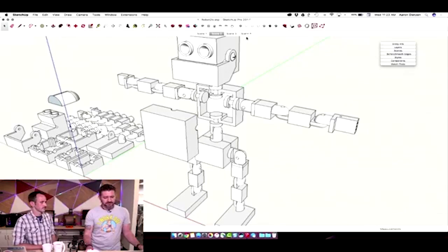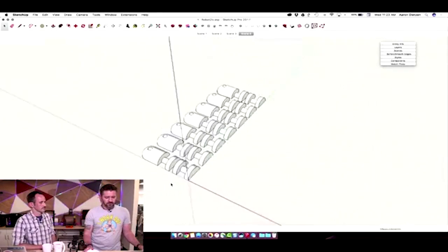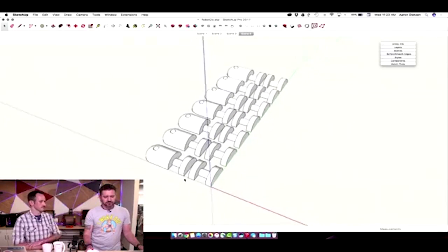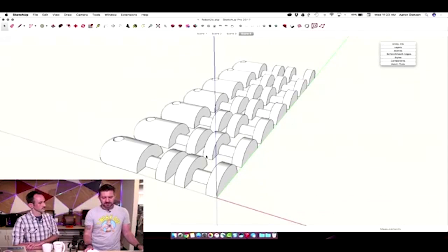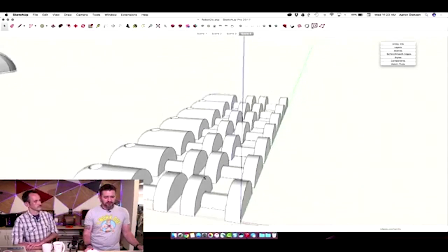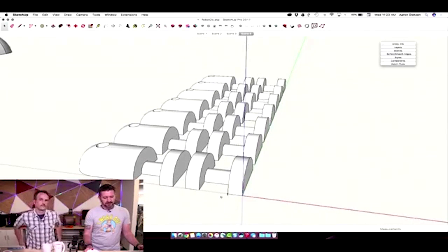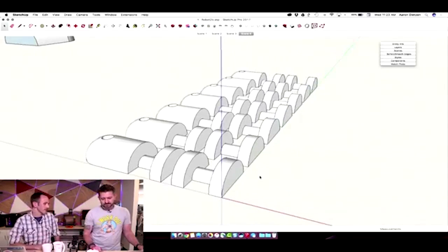So what I ended up doing was finding a way to print so that the grain went the direction of the peg, but at the same time printed my half circles properly. I printed this in 2 pieces, and then I just glued the 2 pieces together to create that final geometry. So in a way, it's kind of like wood grain. Sometimes it does matter which direction you're using the piece.